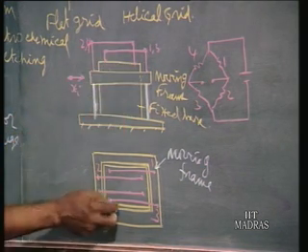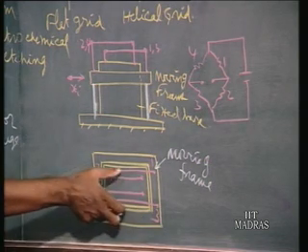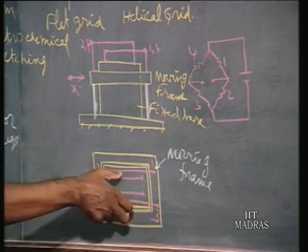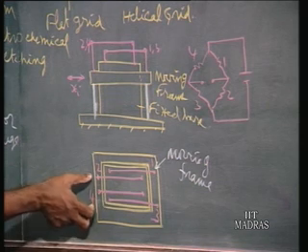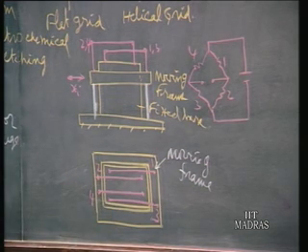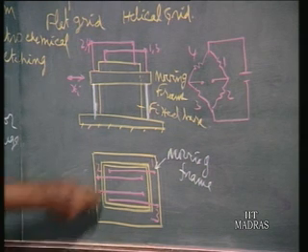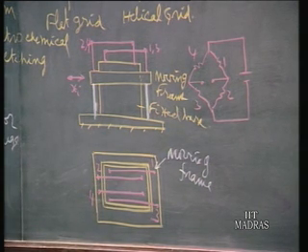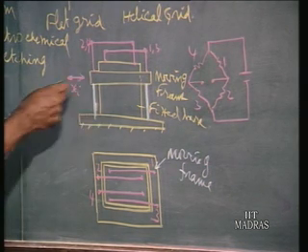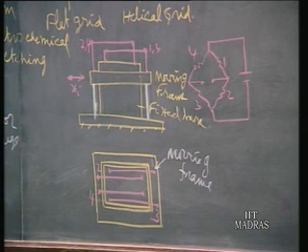Two wires pull the frame in one direction, and the other 2 wires pull in the opposite direction. Net force on the frame will be 0, so it takes a neutral position when you assemble all 4 wires. The wires are assembled in tension because wires cannot take any compressive load; they will buckle. So to use this instrumentation for both directions of motion of the frame, the wires should be assembled under tension.